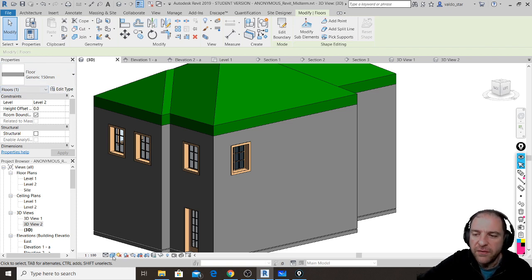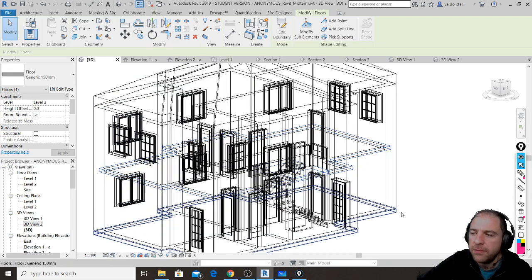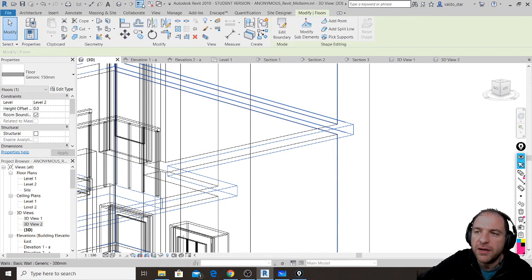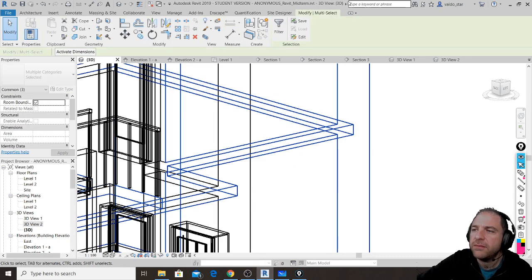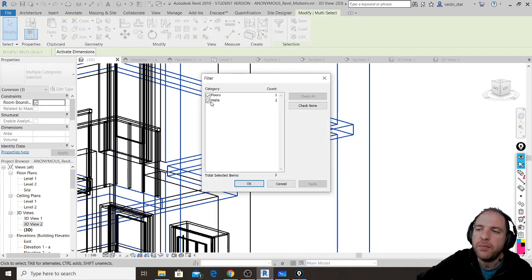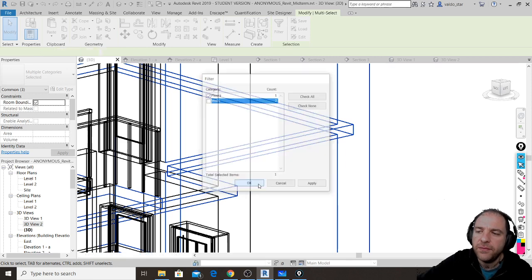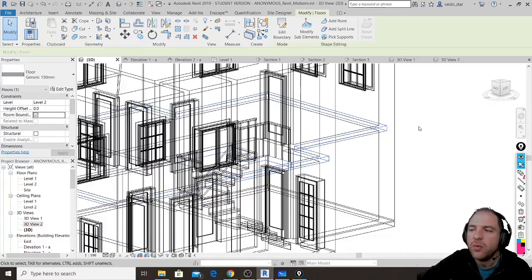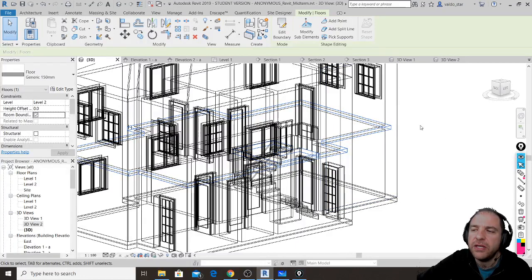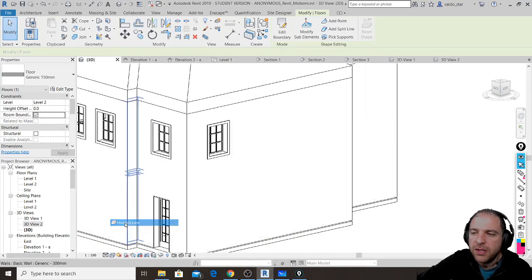And the only thing that remains selected, and I can see here from the properties, is my floor. If I also go in Wireframe, I will notice it's a little bit hard, so I can just make it like this. I select, I filter, I keep the floor selected only, and I will see that my floor is the only object that remains in blue. So if I change it, if I delete it, and so on, I will manage only my selected floor. Okay? And this tool works in whatever view.